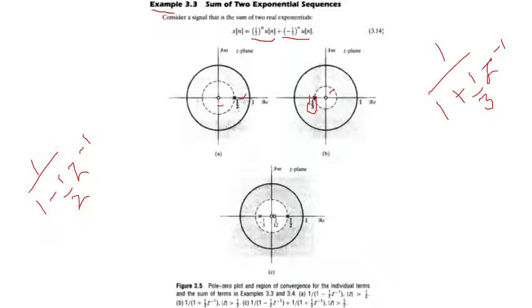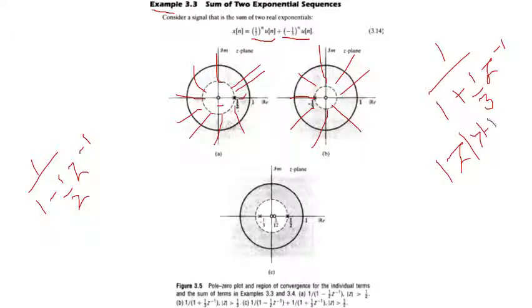Okay. Now the region of convergence for this, because this is right-sided, will be greater than this. So I can take all the values that are greater than 1 by 2. Similarly, the region of convergence of this will be all the values greater than 1 by 3, because the region of convergence is always specified in |z|. So |z| greater than minus 1 by 3 ultimately becomes |z| greater than 1 by 3.